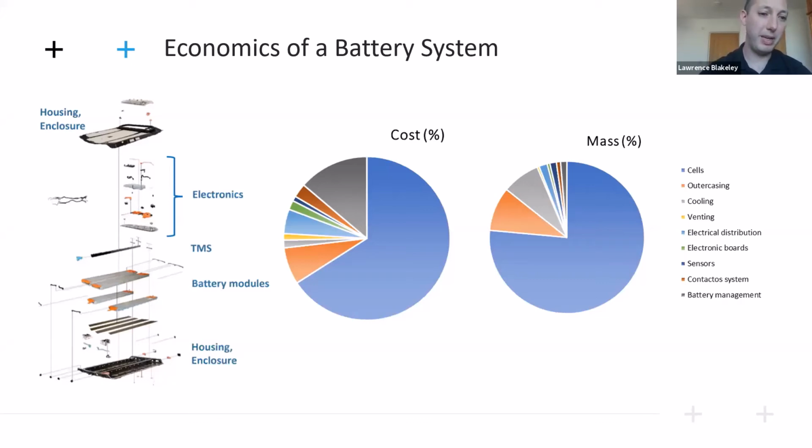What needs to be taken into account is the whole system, because it's not just the cell, it's all of the packaging, all of the bus bars, all the electronics that come together to make the system. So that 400 watt-hour per kilogram won't be 400 at car level. It'll be somewhere, maybe if they're lucky, around 260, 270. It might be slightly higher, but it's certainly not going to be 400 watt-hours once it gets integrated into the system.